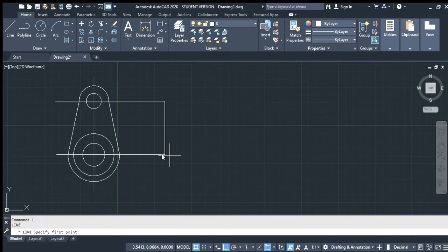Now, if you look at the dimensions, it doesn't tell you exactly how far, but we do know from the circles how wide those extra bits on top over here and on the bottom over here are supposed to be. So we're going to go ahead and hit L for line. Oh, I'm already selected line, sorry. We'll go all the way across. Enter, enter, go all the way across, enter, enter. These are just template lines, so you don't have to worry about them like endpoints. This one goes, enter, and you're basically copying down any line that you see on this one.